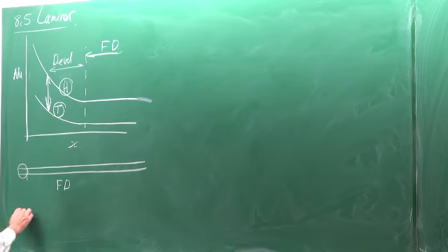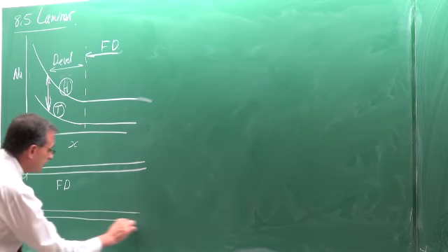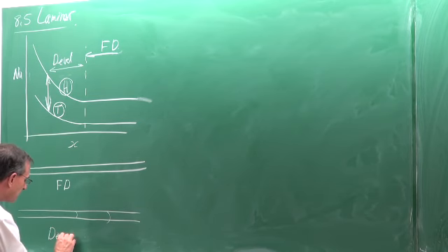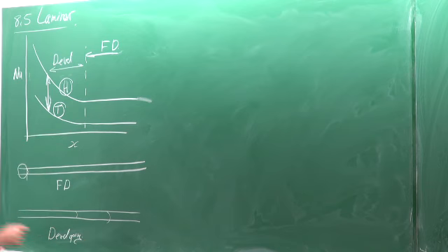However, if the flow is only fully developed maybe halfway through or 75% through, then you have to take into consideration the developing part, and you need to look for equations that can give you those results. They're not always available, unfortunately. In many cases, they are not available in your textbook, but they are available in literature. So there are lots of equations that you need to make provision for all the possibilities that you can get.